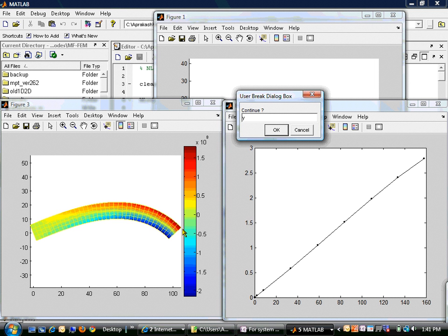Yes, right. So whenever the minimum eigenvalue of the stiffness matrix goes negative or goes to 0, at that point you have instability. And that will happen because this is a geometrically nonlinear problem. The geometric stiffness can either stiffen up the member or make it unstable.